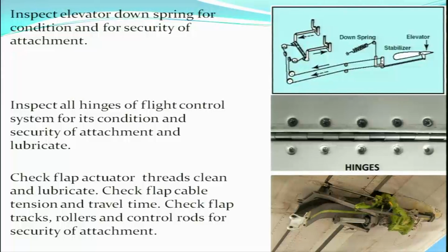Then in the flap system, you can see this is your flap system. This is your jack screw. So flap actuator threads: clean and lubricate. So we need to check, this is the flap actuator, we need to check the threads, clean them and lubricate them.